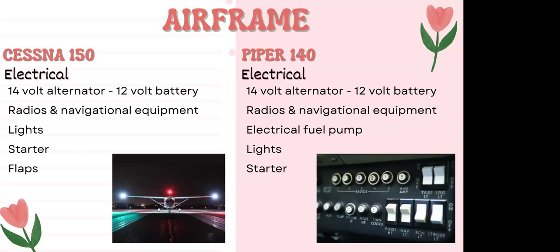So if we had an electrical failure, we also have to consider what that's going to mean for our electrical fuel pump. Now, again, redundancy is great. We've got that engine-driven fuel pump. So if we did have an electrical failure, we're not going to have an engine failure, which is good because that wouldn't make any sense.